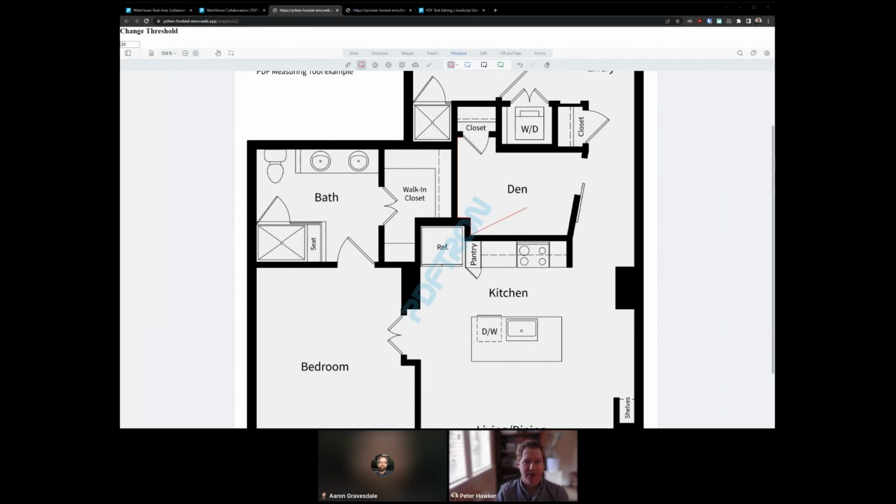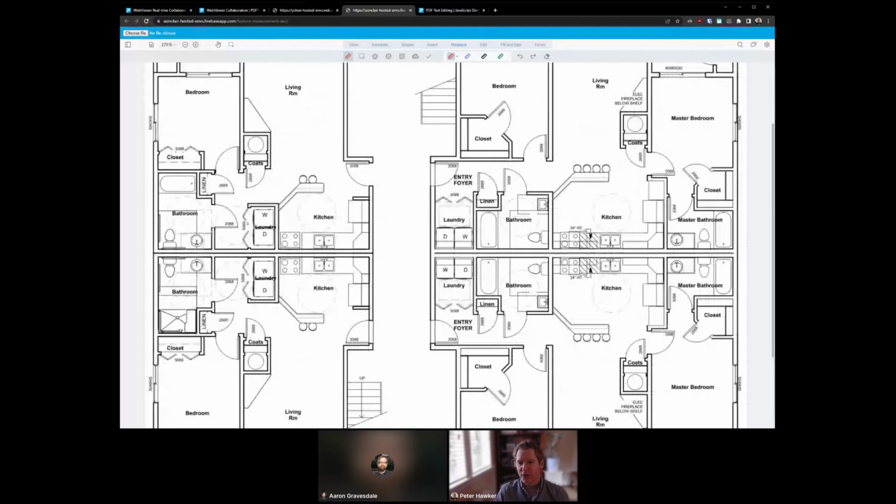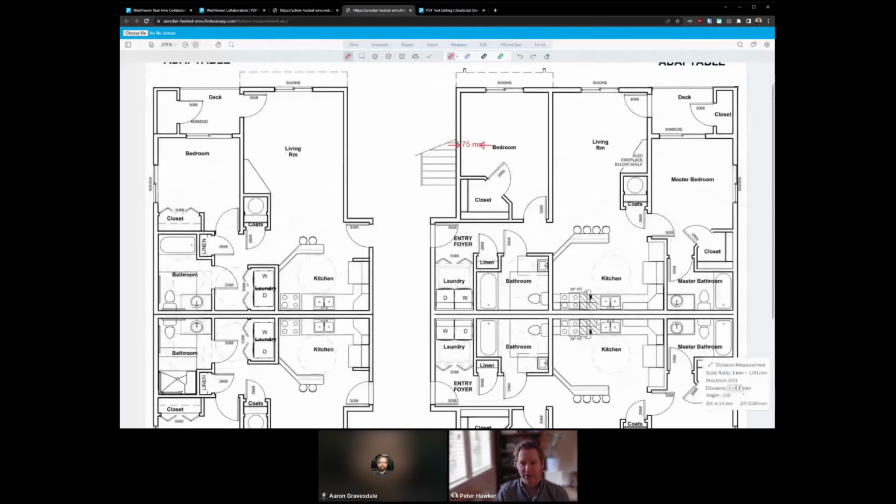Another small refinement that we've made as well is the addition of lead lines to our distance measurement tool. Sometimes we were finding that with our distance measurement, we could obscure the content. So if I'm measuring from wall to wall here, our measurement would actually go across maybe the text or the caption that's already on there. So we've added default support for lead lines with the ability, of course, to extend or move around and rotate. So not a big change, but again, just a refinement.